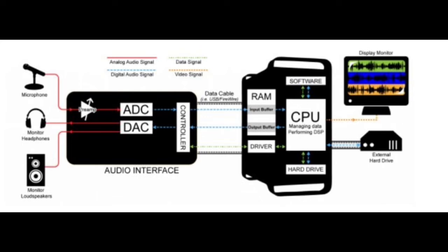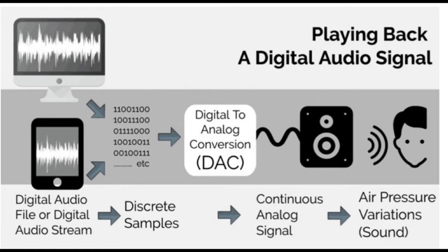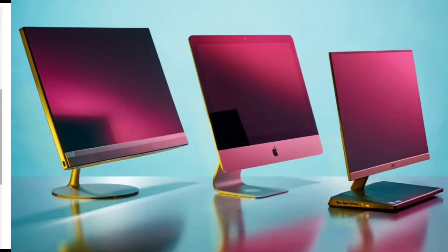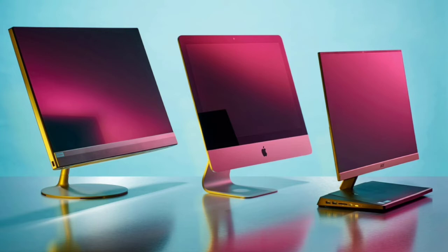Many recording studios record in 24-bit or 96 kHz or higher pulse code modulation PCM or direct stream digital DSD formats and then downsample or decimate the signal for compact disc digital audio production, which is 44.1 kHz, or 48 kHz for commonly used radio and television broadcast applications, because of the decreased frequency and hearing range of humans.